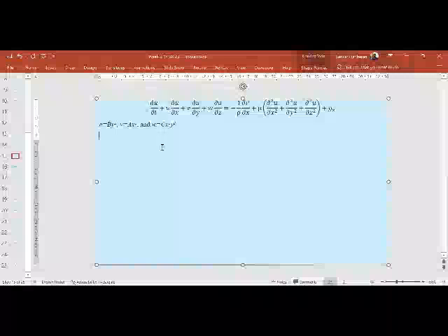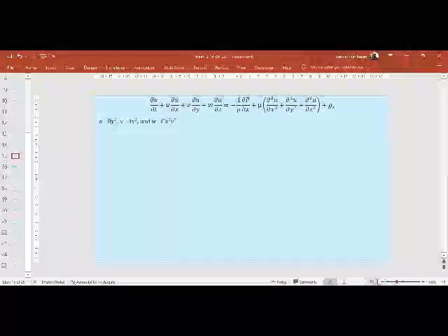So from here we can find out the rest of the terms. You know that ∂u/∂t should be equal to 0. I will just redo it as we were doing for the other one. We know that there is no unsteady term, and u is not a function of x. U is a function of y, therefore this term will exist. U is not a function of z. Minus 1 by rho ∂p/∂x, we'll keep it as it is because that's what we are trying to find out. Mu will be 0, therefore this whole term will go to 0. And we have to neglect gravity.